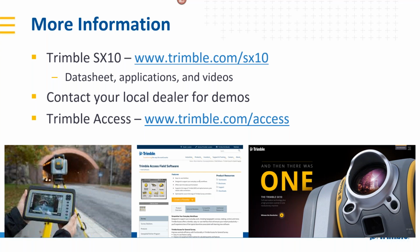So that is all in the spec sheet. Even in Trimble Access, as you select a different scan resolution, you will see the point cloud spacing at a distance. So go to this site and you will see those specs. I just found some information just to reiterate that. At a standard scan setting at 50 meters, you're looking at 25 millimeters resolution. And at a coarse scan setting, it's 50 millimeters.